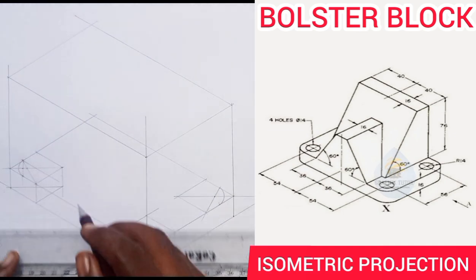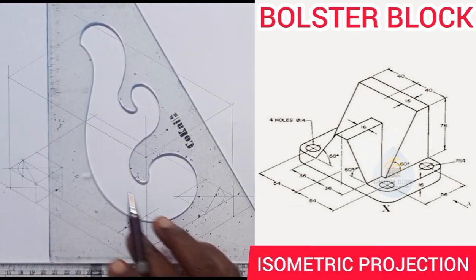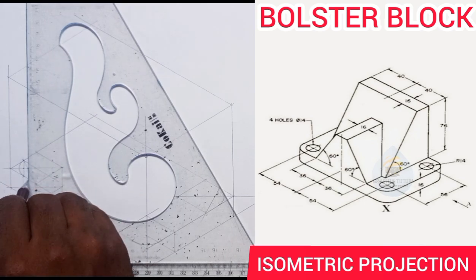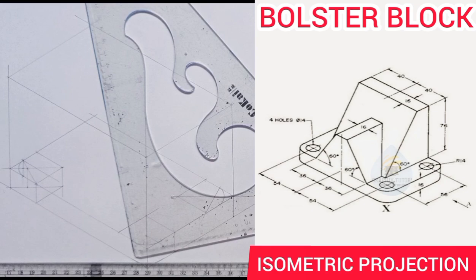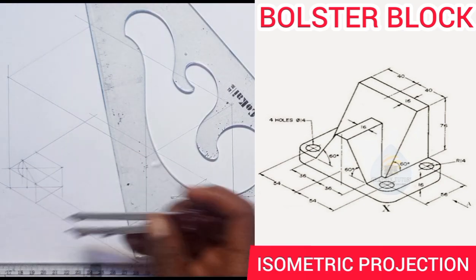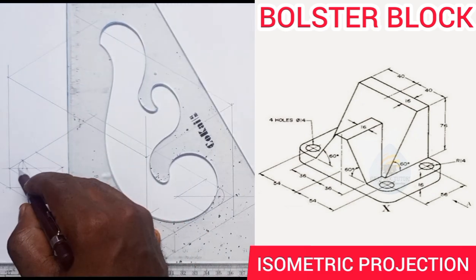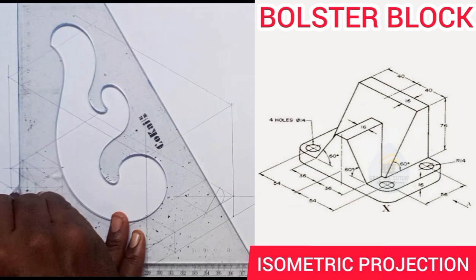Just the diagonal. So transfer that point downward. This point, use your set square, and you bring it downward. So this is where they are meeting. So I'm going to do the same thing at that point there. Place your compass, but the best thing you should just do is at this end here, bring this down to touch here.